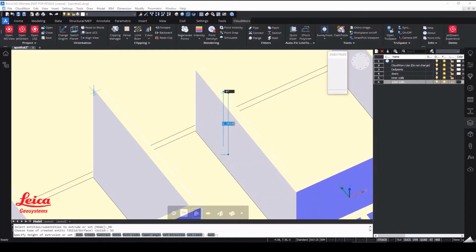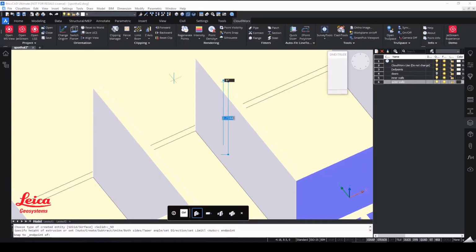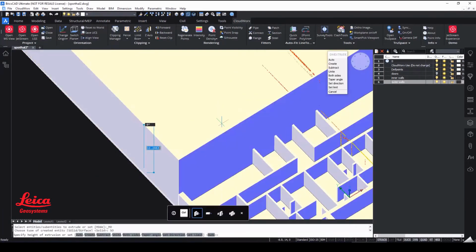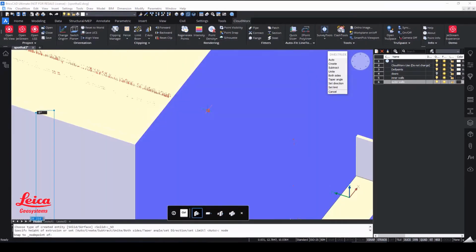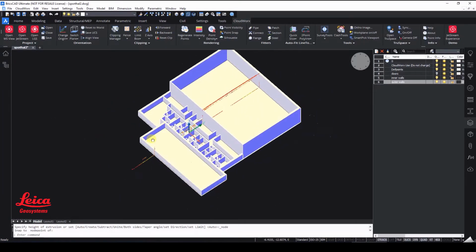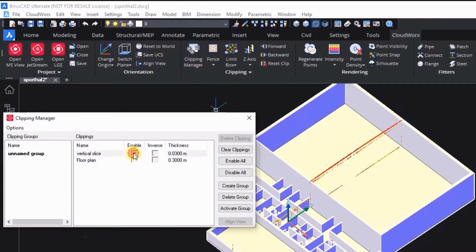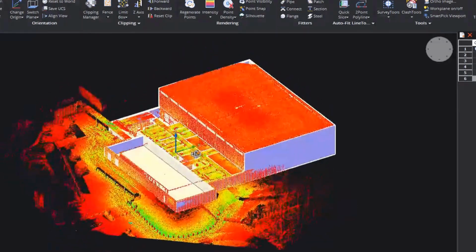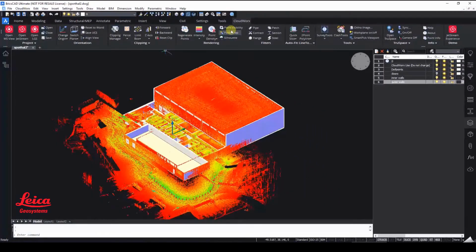And obviously we've got that big area of the sports hall at the back that we can also potentially use as well. What we've done there is use the prior model as the height, and then we're just setting the height for that sports hall area as well, again using the point cloud to specify the right location. And you can see the model is beginning to take shape, and this has all been done on the basis of our reality capture data. And obviously if we turn all the point cloud off, then you can see the model data alongside the point cloud. It's looking rather nice.